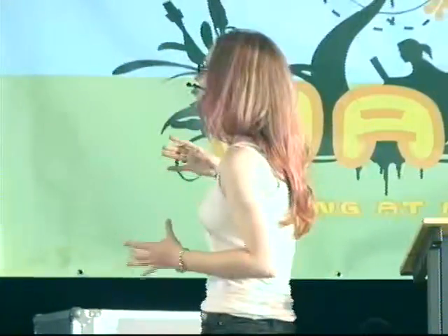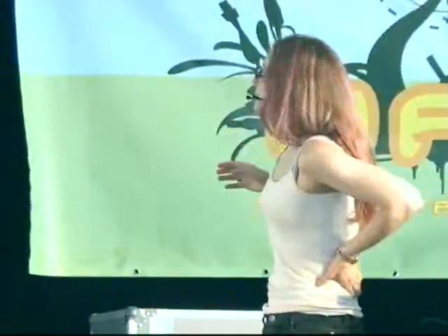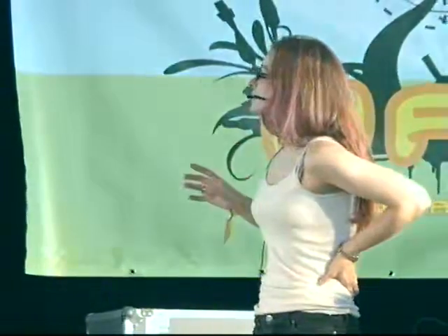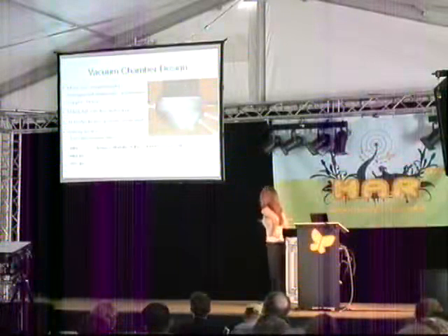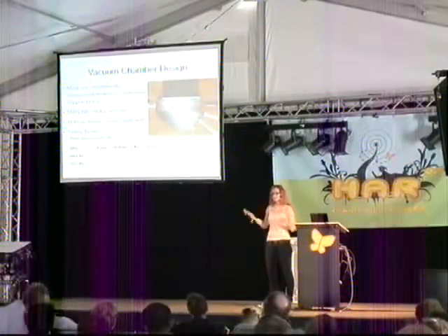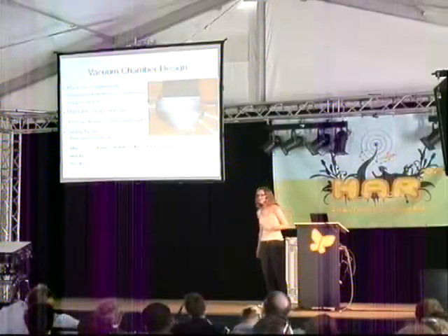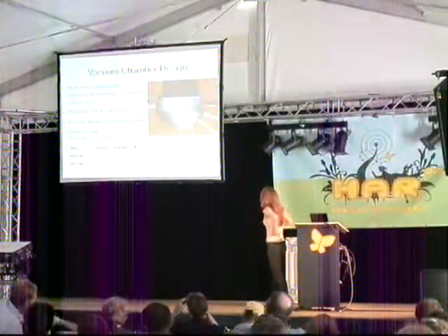I did a bolt pattern of, I guess, 16 for that radius. Just make sure you don't have any large stress concentrations in the material. It works well to do an aluminum body and then brass bolt holes through it. Just from experience, aluminum screws don't work or exist at these pressures.